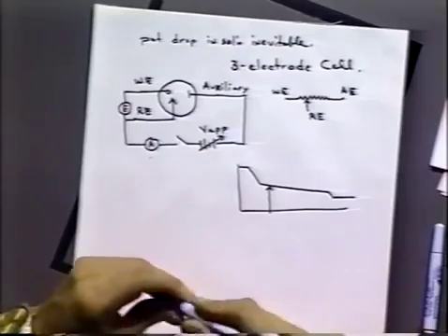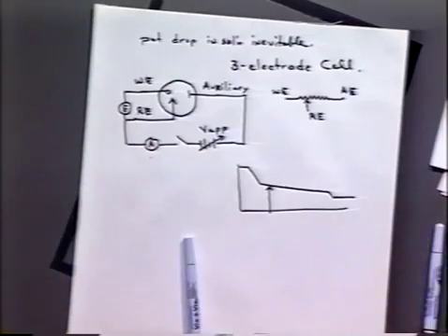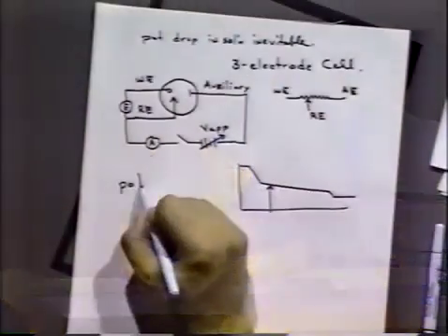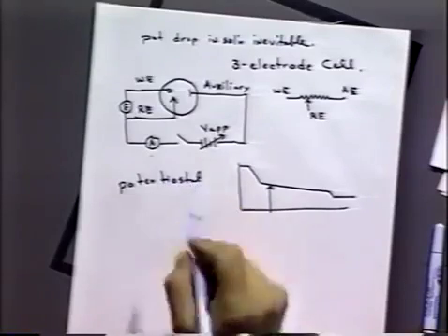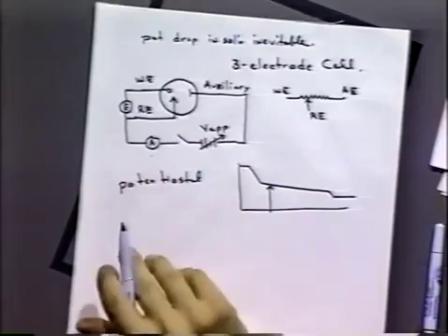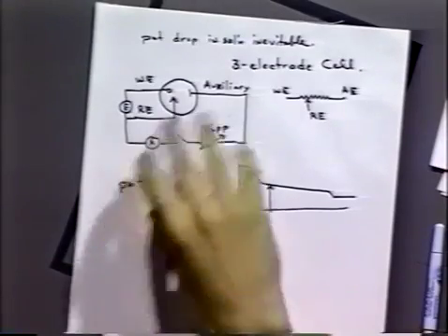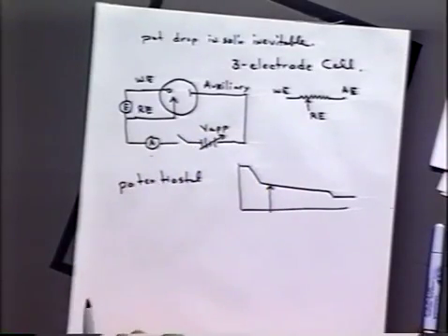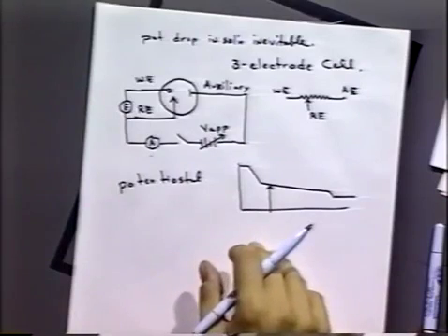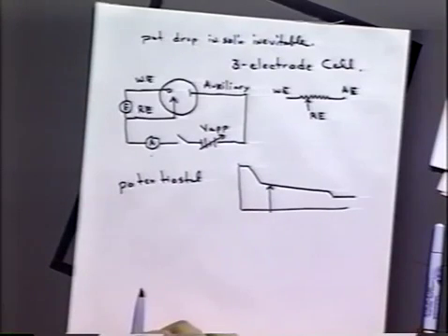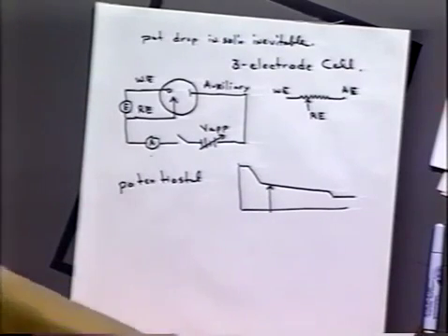Now, I've talked about doing that in a manual way by sitting there adjusting knobs and measuring the potential, but in fact you can build an instrument that does all that automatically for you, and so you can use what they call a potentiostat, which is just designed to do that job for you. It'll use a reference electrode to measure the working electrode potential or close to it, and then adjust the auxiliary potential to be what you need it to be. And those can operate at very high frequencies, up into the hundreds of kilohertz region, to get good potential control of your electrode all the time.